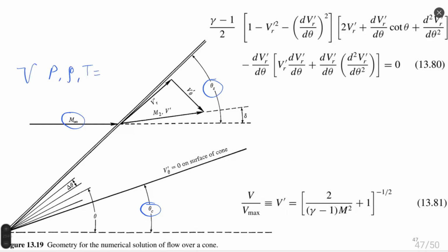Okay, I will include also velocity here, constant. All flow properties constant, as we might observe from experiment, as we might see from CFD analysis. Outside of the shockwave, there is no sense to calculate, because all flow properties stay constant and equal to undisturbed infinite conditions. Can be defined by Mach number and flight altitude, for example.